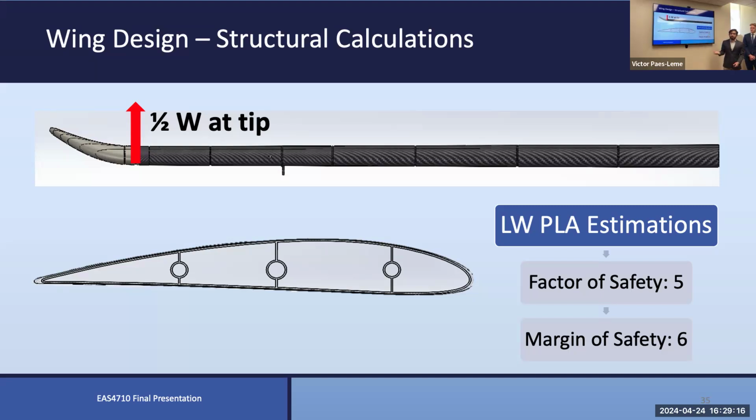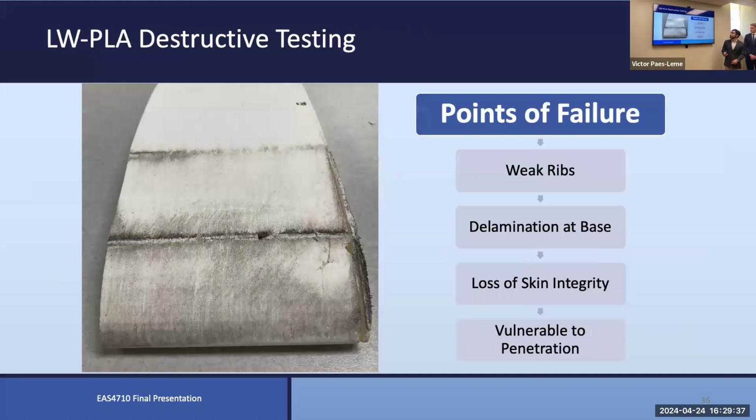This gave us a good amount of comfort when operating in different turns, and we found that we were operating within a margin of safety of 6. This gives us good security that our wings are structurally sufficient to fly within our flight regimes. We're not pulling any acrobatics, and we have a lot of play and give with these values.